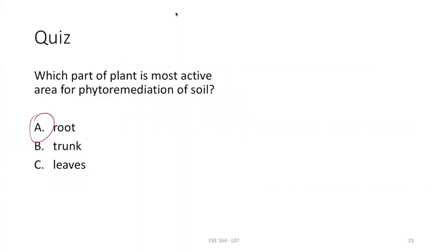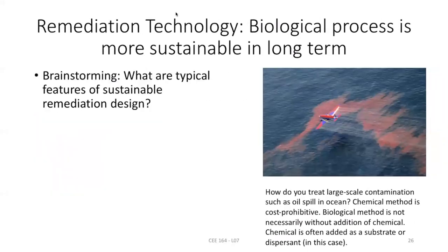If your pollutant is way deeper in the soil at your site, phytoremediation is not effective, because the best grass we know can migrate a maximum of 6 feet. Some could go to 12 feet, but that's very rare. So 6 feet, or 1 meter, is mostly the root zone. Anytime your pollutant is below that, you can't use phytoremediation because the roots can't reach there. So that's one thing to think of. That's the whole reason I put it there.